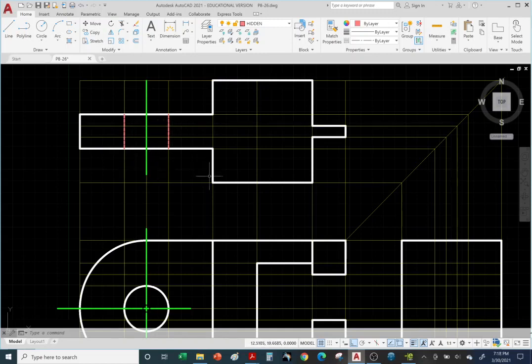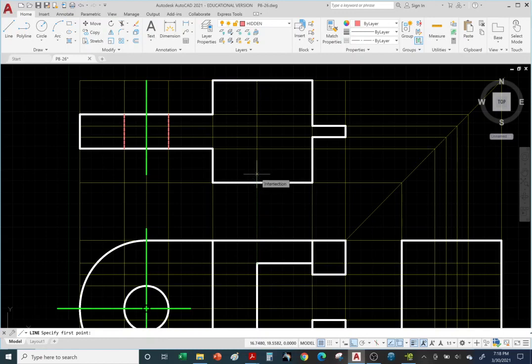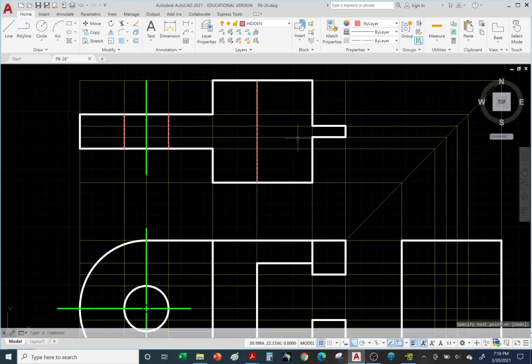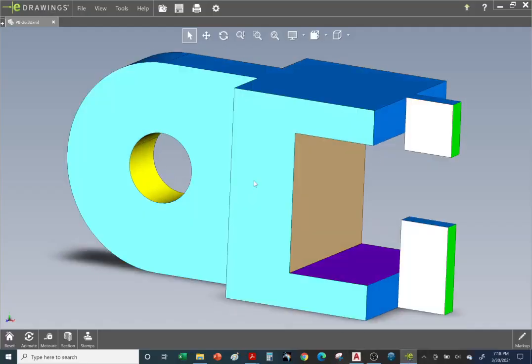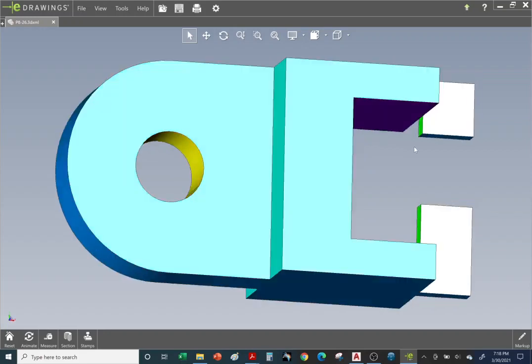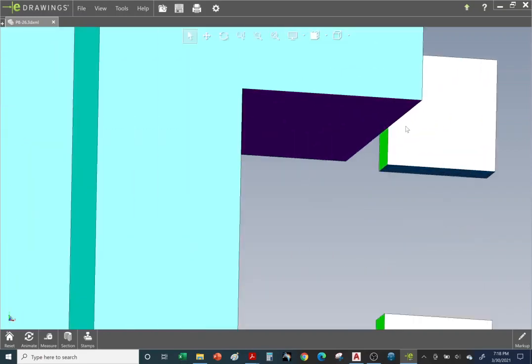It's okay. All right, so now we have a red hidden line right here. So use Line Command, and from this vertex, go straight up. And right click Enter. And also finally the red hidden line here. Just to prove it to you that we do have one there, if we look under here, there's this edge that we cannot see.